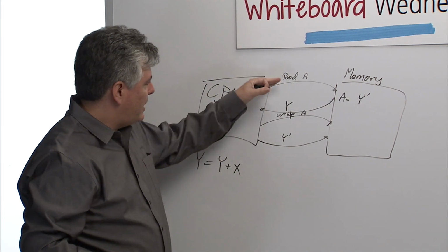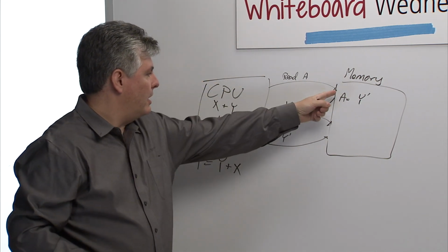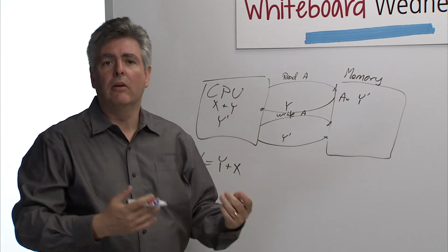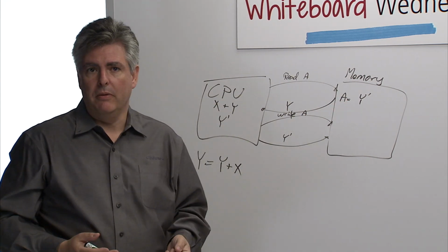So I've had to move data. I've had to send two commands across the bus, and I've had to move this data all the way over here and then move it back again. And all of those things take energy, and they also take time, and they take the attention of the CPU.